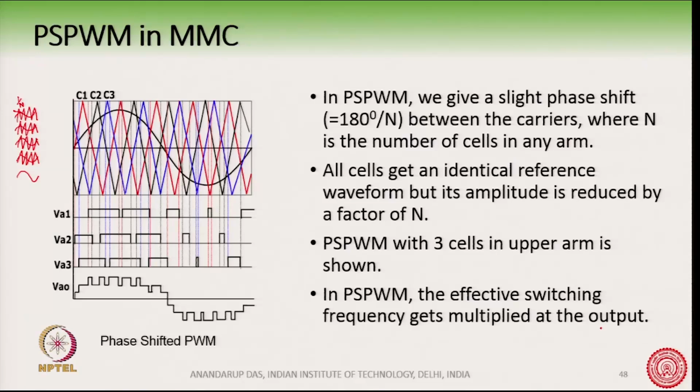Okay. So, if you do this phase shift PWM, MMC has a large number of cells, and you can also do the phase shift PWM with MMC. So, this reference signal here will be given to each cell.